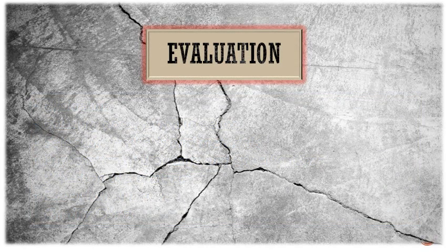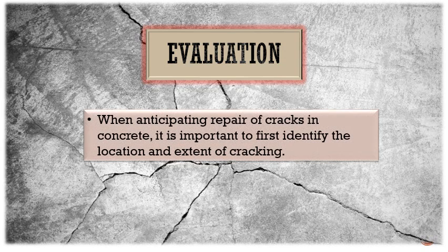First is the evaluation. When anticipating repair of cracks in the concrete, it is more important to first identify the location and extent of cracking. Evaluation should determine whether the observed cracks are indicative of current or future structural problems.